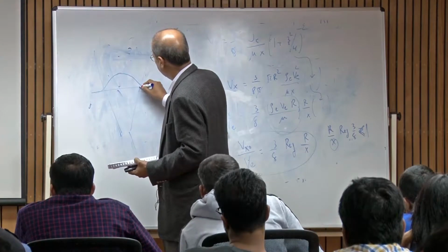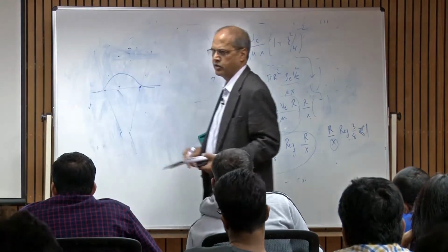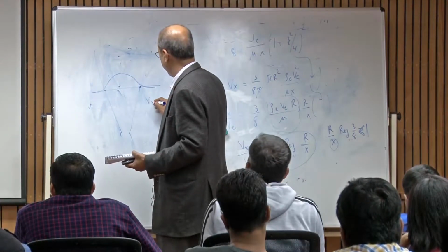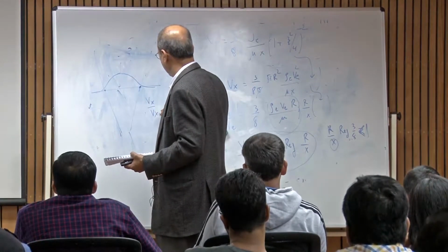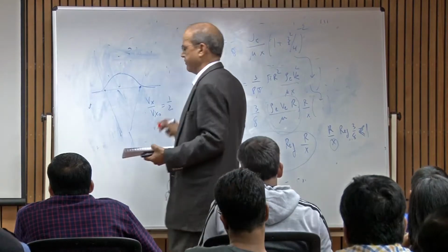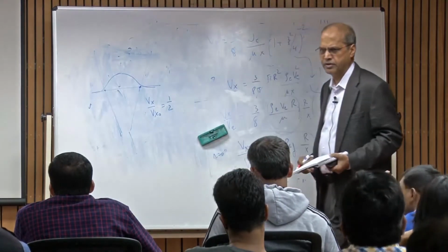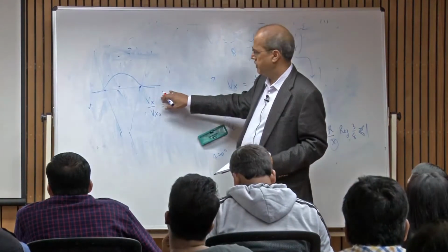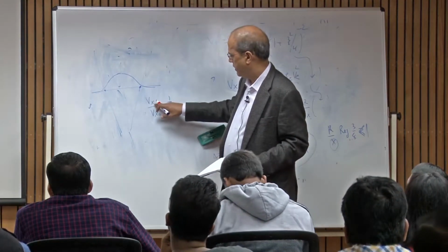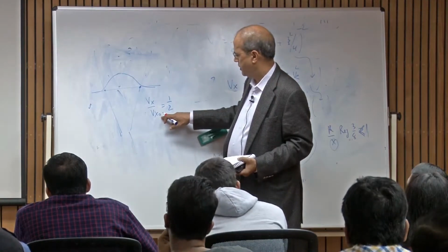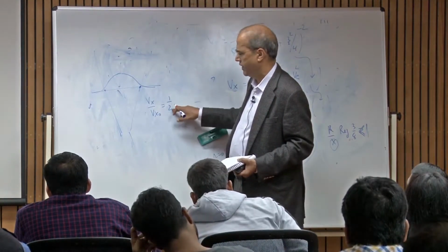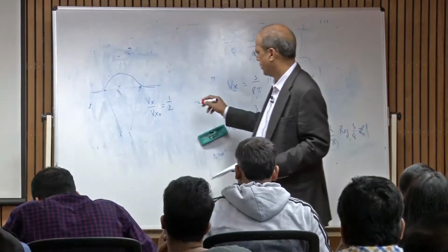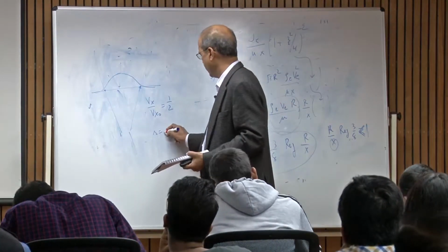So how do you define this jet radius or the spreading radius? We define it by saying that Vx over Vx0 is 1/2. So this is the Vx value where this ratio becomes 1/2. We define that as the spreading radius, and we call that r there equal to r 1/2.